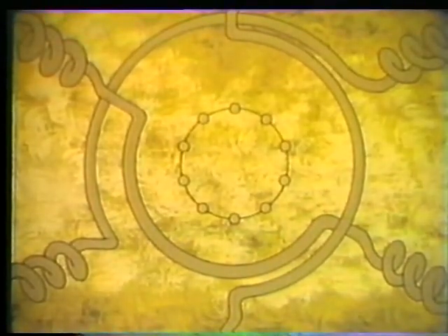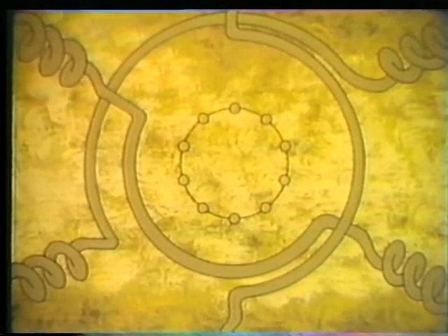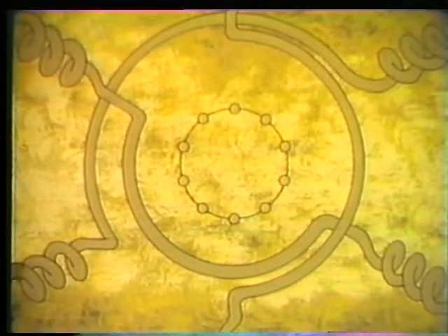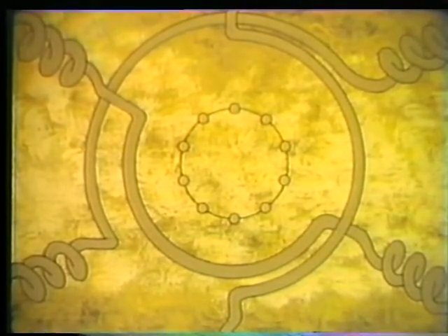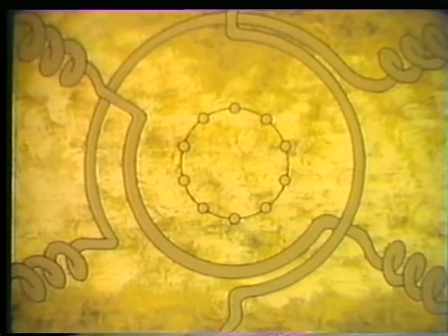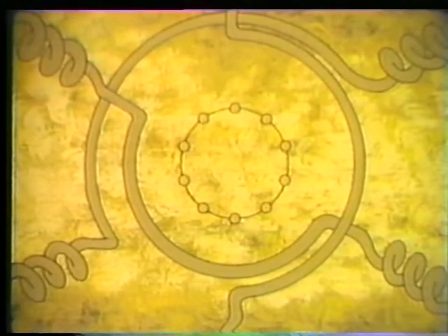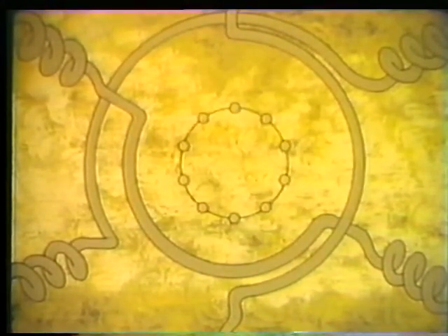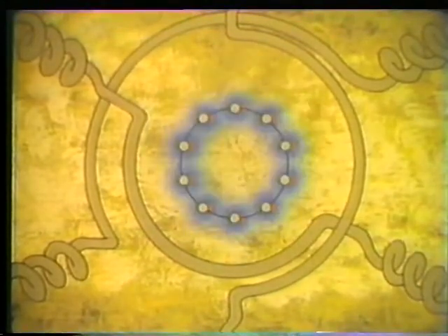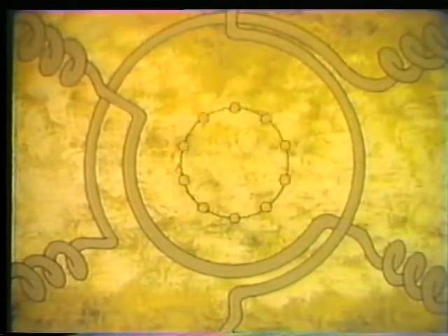Whenever there is relative movement between a conductor and a magnetic field, there's a voltage induced in the conductor. The rotor, you remember, has conducting bars. Relative movement between the stator's field and the rotor bars induces a voltage. Because the magnetic field of the stator is rotating, the voltage induced into the rotor creates a flow of alternating current in the rotor bars. As the stator's magnetic field continues to rotate, the current produces a magnetic field in the rotor which expands and collapses. And this pulsating field interacts with the stator's rotating field, causing the rotor to turn in the same direction.